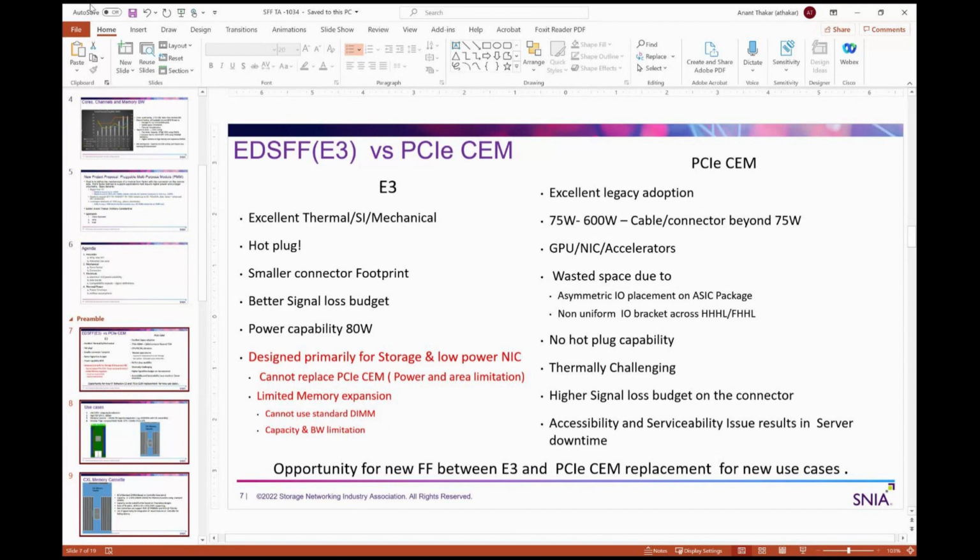I think the question is going to be, what is the smallest unit of memory buffer configuration? Controller plus 2 channels, or is it going to be controller plus 4 or 8? Correct. Just looking at the history of what happened with NVMe SSDs, typically it tends to be at a certain PCI lane count, and then you normally try to scale out. Correct. This is more of a scale up solution.